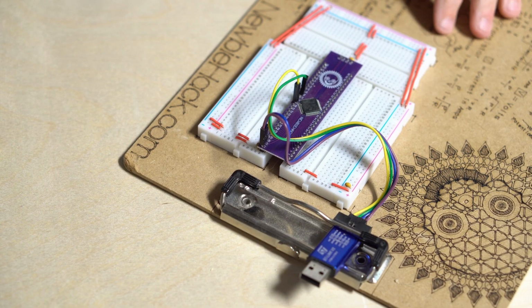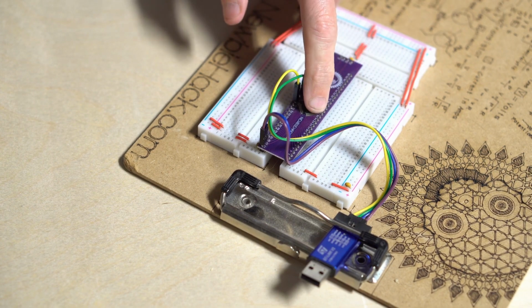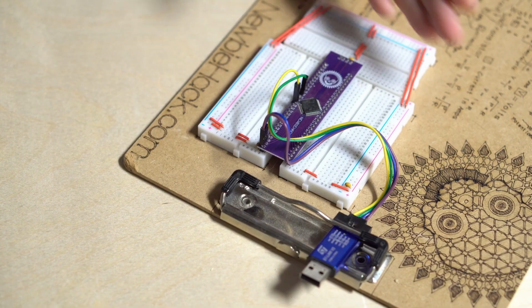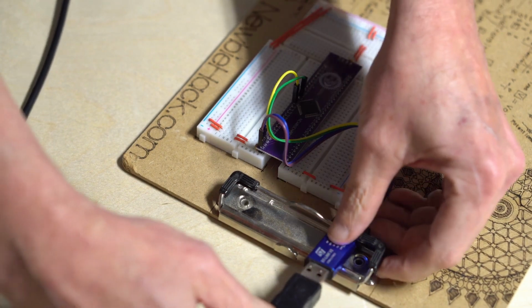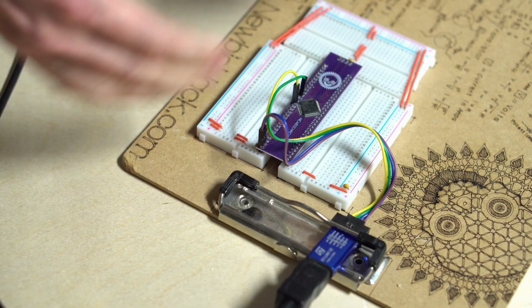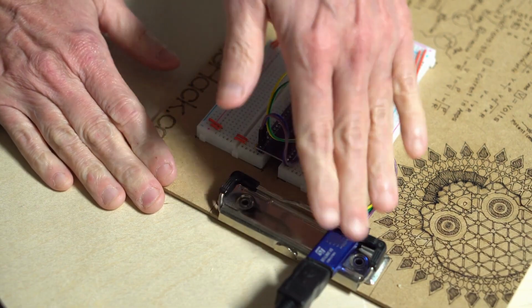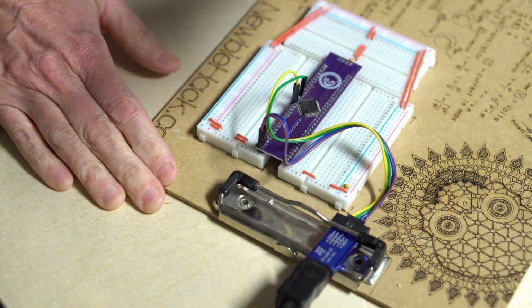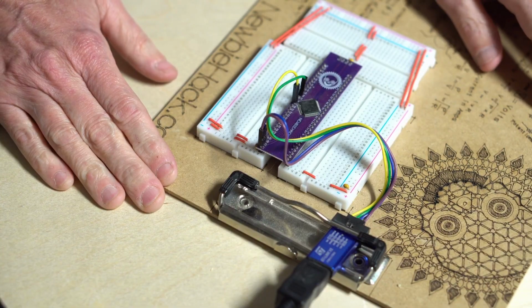Now we are ready to run the project, which is transferring the program to this microcontroller and monitoring the variable we just created. To do this, we need to plug the computer to the programmer, and you'll hear the notification on the computer that something has been plugged in. If this is the first time you're plugging it in, it'll take a little time to install, so just follow the prompts you have with Windows to make sure it's installed correctly.